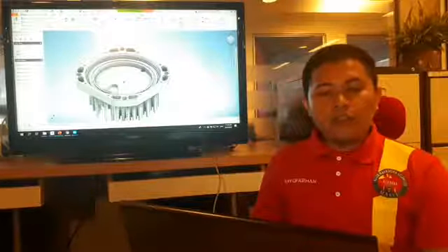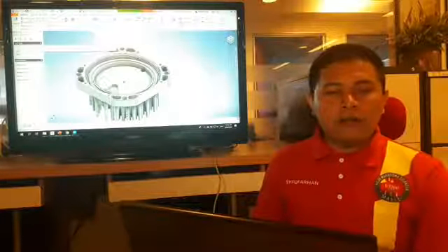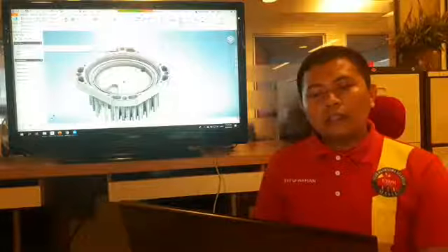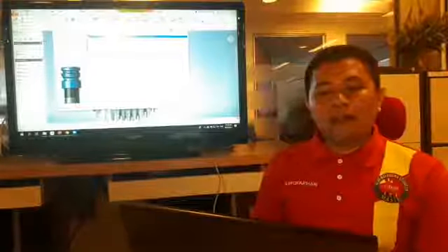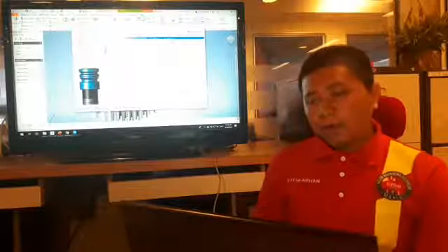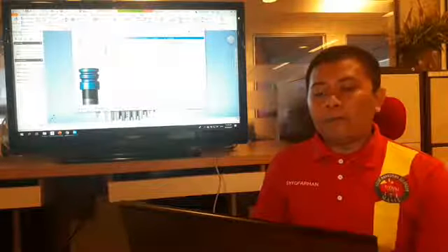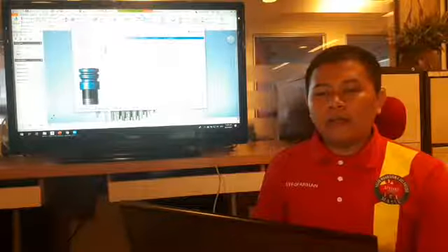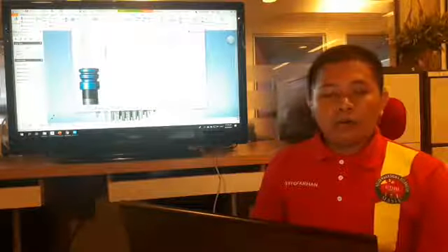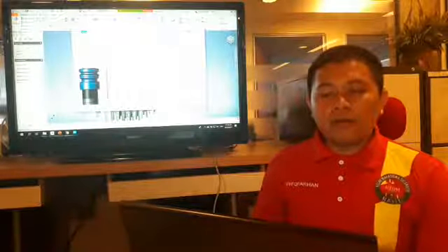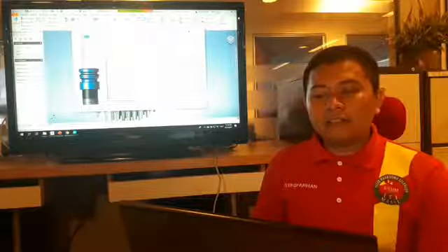Okay. So I choose the proper tools by simply clicking on tools. After that you will have a tool library, so you can choose your proper tools. My suggestion is to go over here to by type and choose any drill.